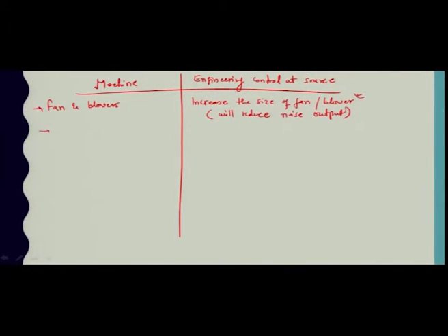If the sound is coming from, let us say, vibrating machinery, we have to provide better balancing of the components. Such noise often results from imbalance of rotary or rotating members.